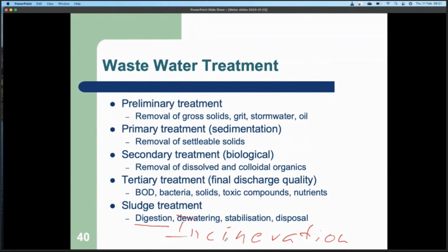So in Switzerland, for example, all sewage sludge is to be thermally recovered, whereas Sweden, I believe, still has a policy to try wherever possible to recover all sewage sludge through land application, because they're saying that there's a lot of good nutrient in the sludge, particularly nitrogen. In order to get this nitrogen, normally you have to spend a lot of energy to get it out of the air and make it into nitrate and ammonia and these sorts of things.